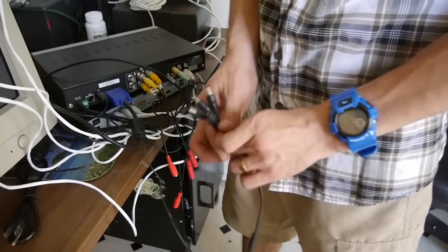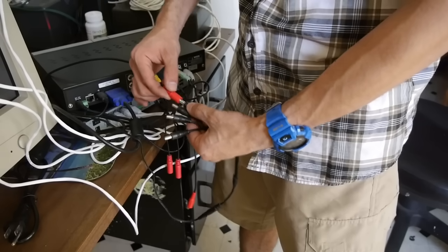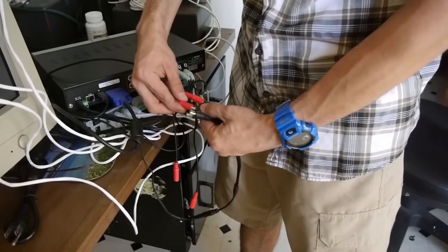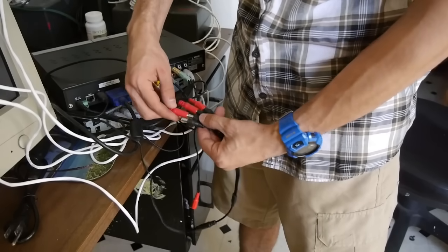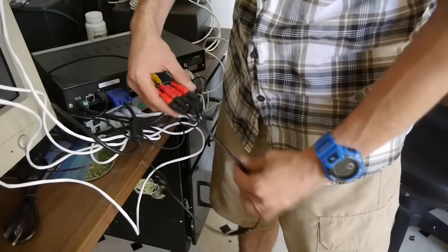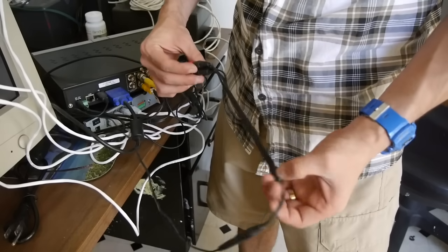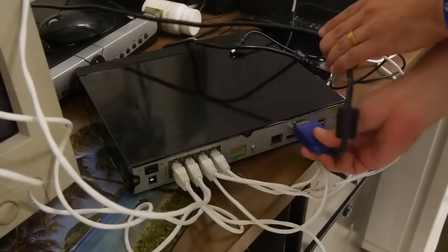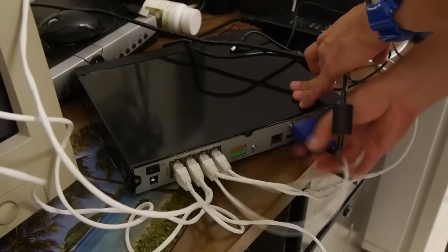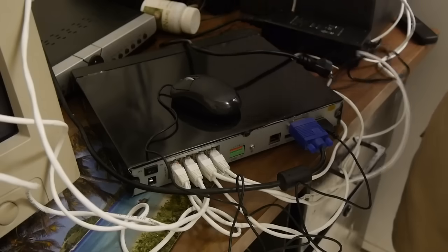Also, connect the camera power cables to the camera's power source. On multi-camera systems, instead of there being a separate power source for each individual camera, there will be one or a few power sources that connect to many cameras at a time. Here I have a power source with an adapter that connects to 4 cameras, and each camera's power cable connects to this. Now connect the monitor to the back of the DVR. Connect the mouse that's included with the DVR into the USB port on the back.